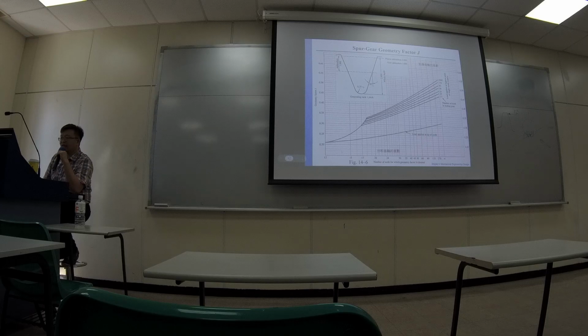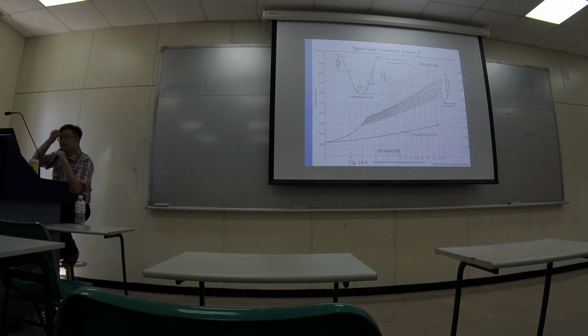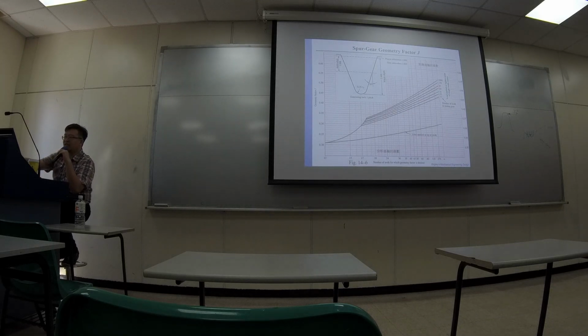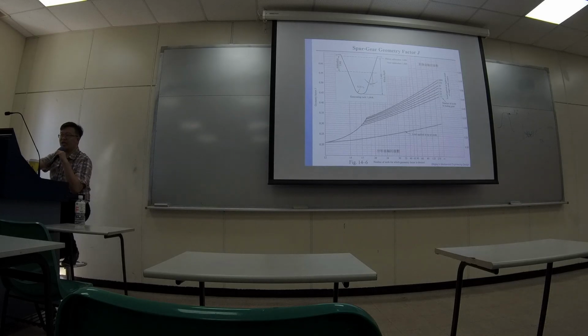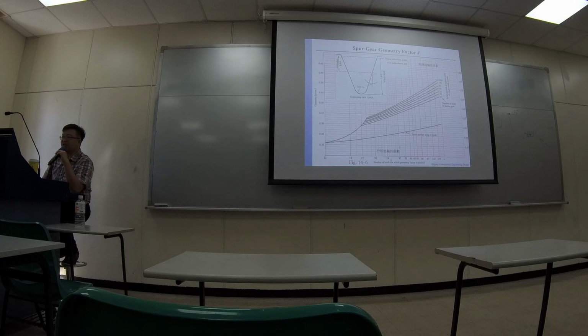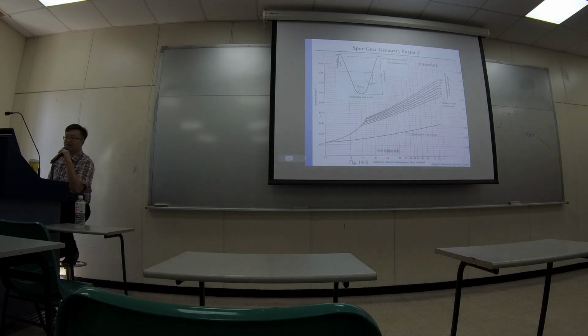And in this table, here is the number of teeth for which the geometry factor is desired, and this is the number of teeth in the mating, the conjugating gear. So it depends on how your gear is conjugating with the opposite gear, and the number of teeth affects this geometry factor.